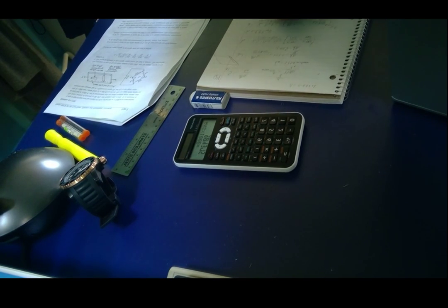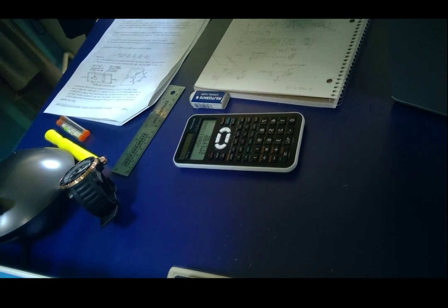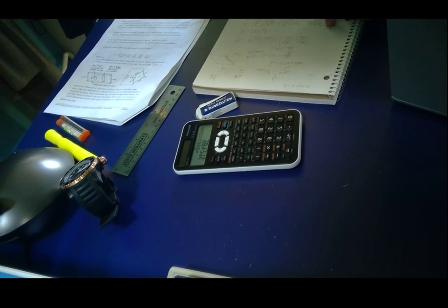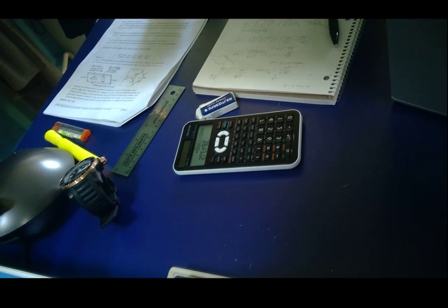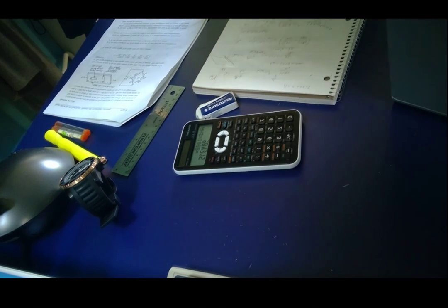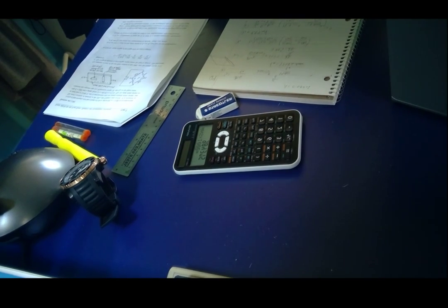Because if you get the equation, if we say that Vs R2 R3 divided by R2 plus R3 squared becomes, I don't know, something called beta, then we'll have beta times an equation where R3 is a strain gauge and R2 is a strain gauge, but R3 is placed on the metal that is being strained and R2 on the metal that is not being strained. Then delta R3 has two parts: the delta R strain and the delta R temperature divided by R, minus delta R temperature, because the second strain gauge will have only the strain made by temperature.